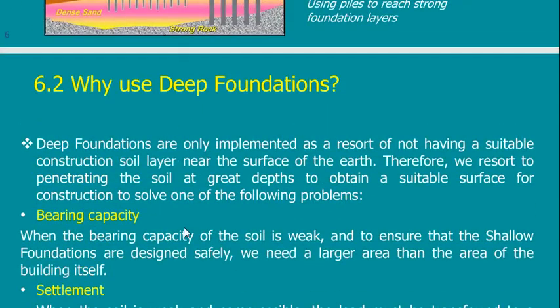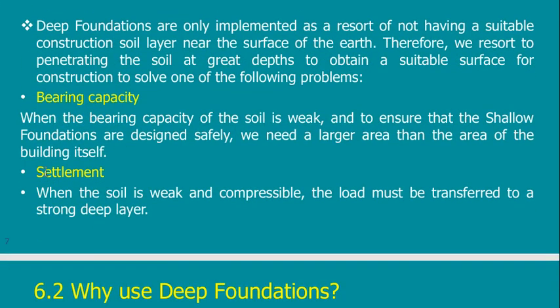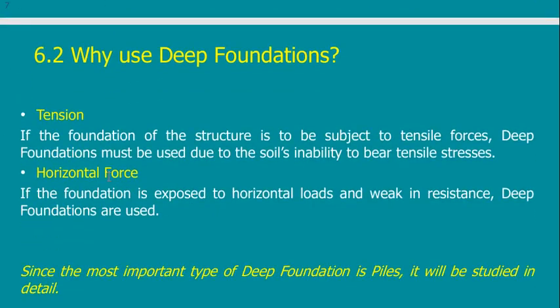When to use deep foundations? When the bearing capacity is not adequate, when the settlement is excessive, when I have tensile loads, because as we said before, shallow foundations cannot carry tensile loads.